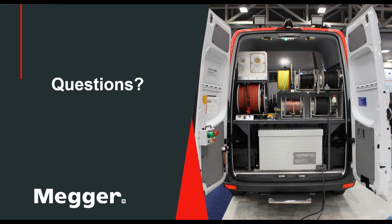So your next question, Henning, is could you please provide an example of a voltage that would be used for breakdown tests for a 35 kV cable? Well, if you have a 35 kV cable, it's basically the same as what we had just talked about. When you run a breakdown test, you're not using a defined voltage. You're using the voltage capability of the unit to run it basically all the way up. So in this mode, you would set the highest voltage you have on the unit. Let's say in the case of the ST25, you have 30 kV, you punch in 30 kV and you turn it on.